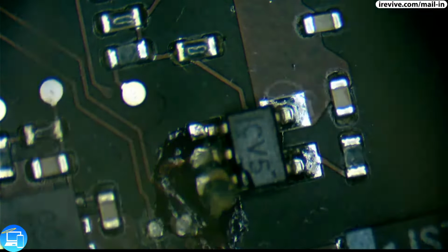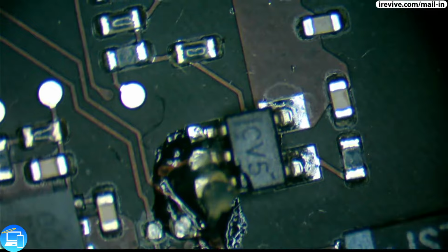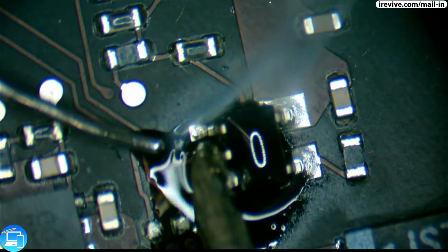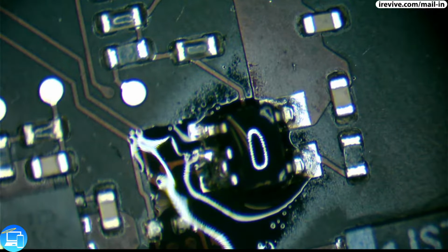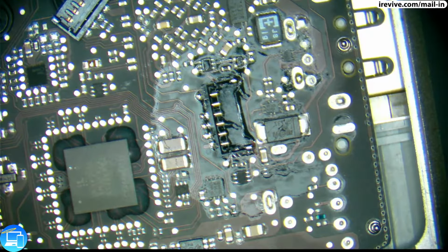So what I'm going to do is just very quickly get a bead of solder, just glob between the 2 pins. Just like that. So now our PLT Reset L is shorted to ground. So now we are at the point to where we can go back over to where our Lattice Molex terminal is at, and we can go ahead and plug our connection in.